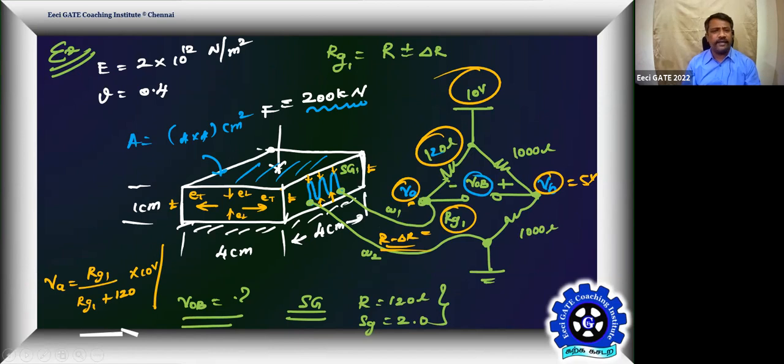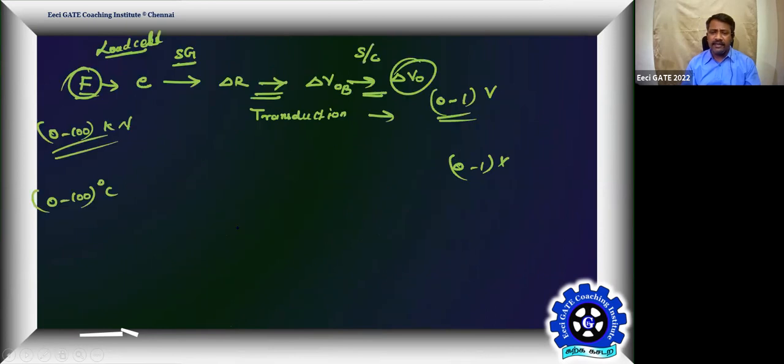That signal is very vital in strain measurement, because the strain we are going to get from the load cell is going to be in the order of micro only. So the bridge is not going to produce a strong potential. That demands a lot of signal conditioning work. So much amplification is needed during signal conditioning. By default, it is achieved by instrumentation amplifiers only, because they are capable of having a gain up to 2000.